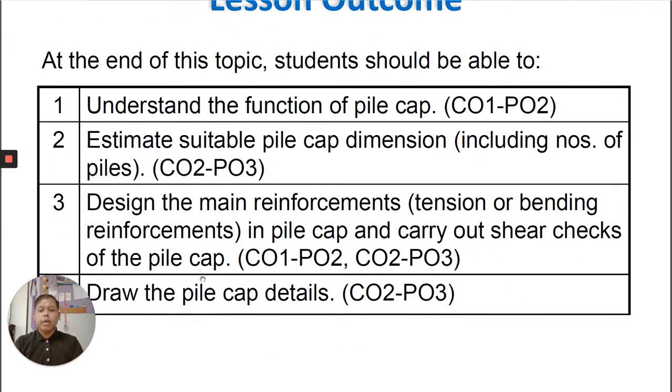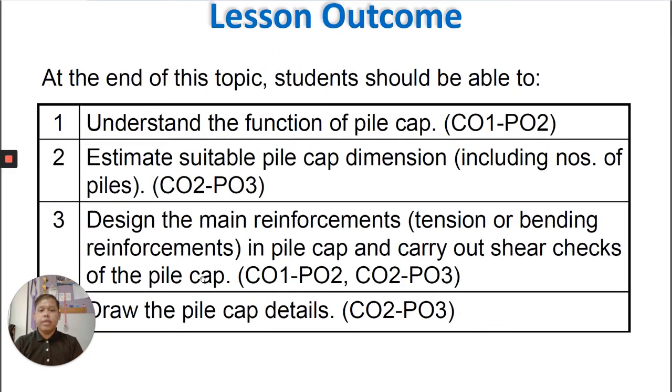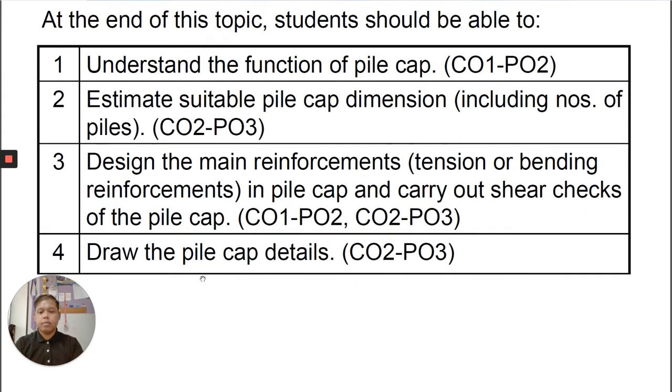As a student, at the end of this lesson, you should be able to understand the function of a pile cap, estimate suitable pile cap dimensions including the number of piles, design the main reinforcement, tension or bending reinforcement in the pile cap, and carry out a shear check of the pile cap using beam theory and also truss theory. And the last one is to draw the pile cap details.